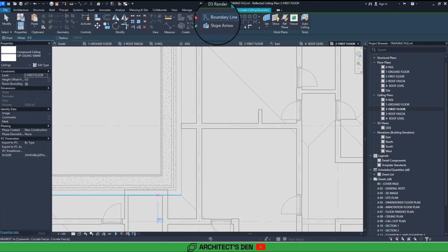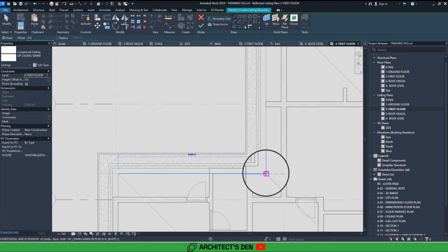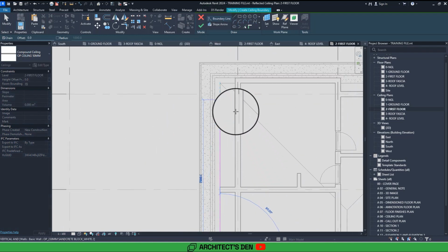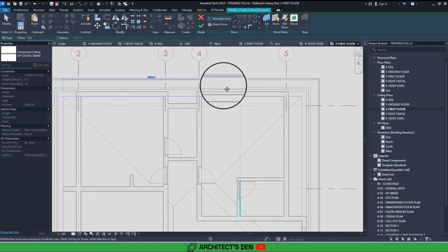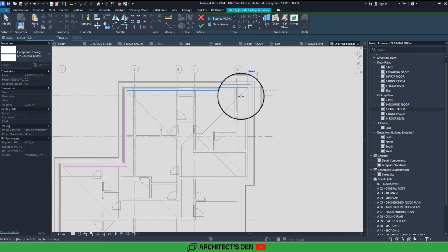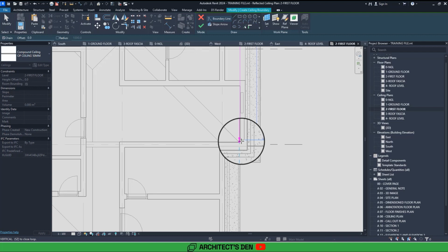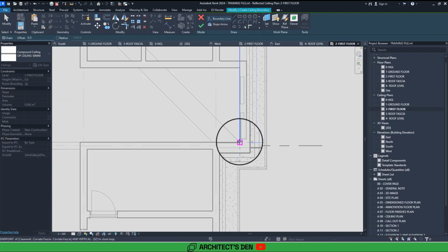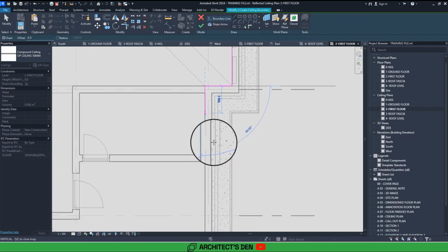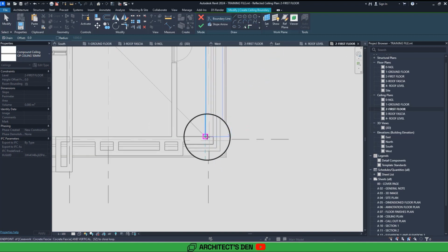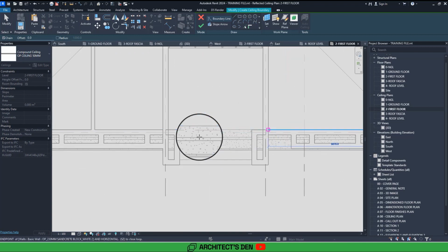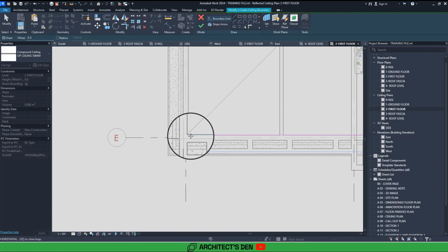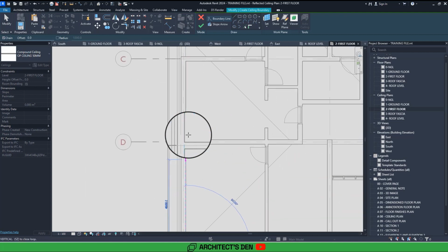I can do that on the internal spaces from the wall beam all the way through the space. So I'm just clicking the sketch through the internal spaces, through the internal walls, because your ceiling will be on the internal walls, since we use the concrete fascia on the external.